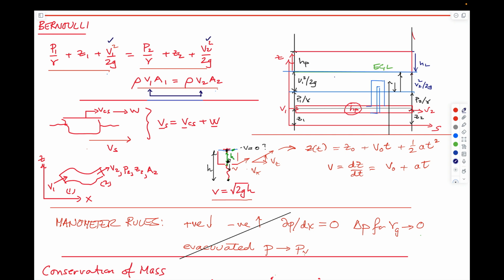and atmospheric pressure, we know that the standard result is just that the velocity is the square root of 2 times gravity times the elevation change between that point relative to the free surface. It doesn't matter if it's squirting out of the bottom vertically or out of the side horizontally or at an angle, it'll still be the same velocity as we get from Bernoulli. We know that if it's inclined, then it's actually a streamlined velocity that we calculate. So this is a streamlined velocity.